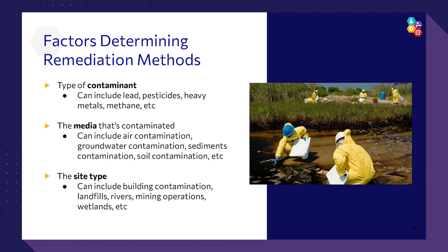And not every remediation technique is going to be used at every site. For a site that has oil or petroleum impacts, you are not going to be able to use all different types of technologies. You also have to consider what is the intended goal for the site or the long-term land use. Is the site just to go back to steady state because it's still going to be an industrial site? Or are you trying to clean up the site to make it a future development? Maybe it's going to become a playground, or maybe it's going to become a parking lot. So understanding the future land use is really critical to a remediation process.